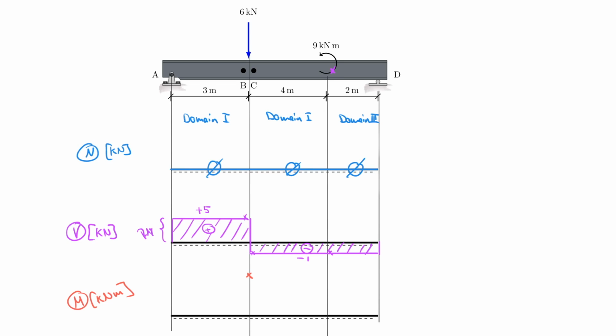And I also calculated the value right here with positive 2, so that I can actually draw a little cross right down there. And now it's very tempting to say, if it's plus 2 here, then maybe it's plus 2 on this side as well, because that was the case for this location. But notice that here at B and C, we're actually dealing with a concentrated force, whereas here we are dealing with a concentrated moment. And so the concentrated moment will have an impact on your equation if you extend the cut that we did actually for the right side of the system.